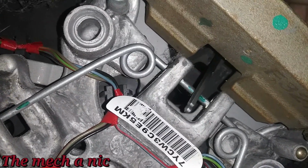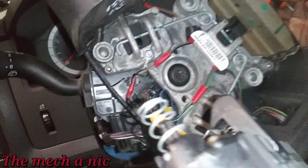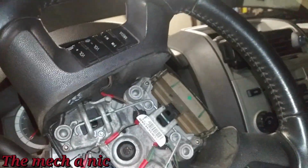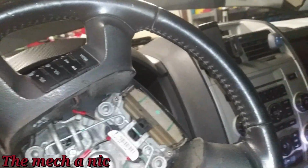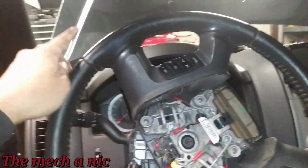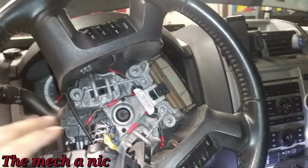Now imagine trying to do this without being able to see anything, because it would be covered up by the airbag. It's complicated. Trust me, it's going to eat up a ton of your time, and it's just going to get you super frustrated. So the way that I found to do this is, number one, make sure your battery's disconnected. Don't touch any of this stuff with the battery connected up front.